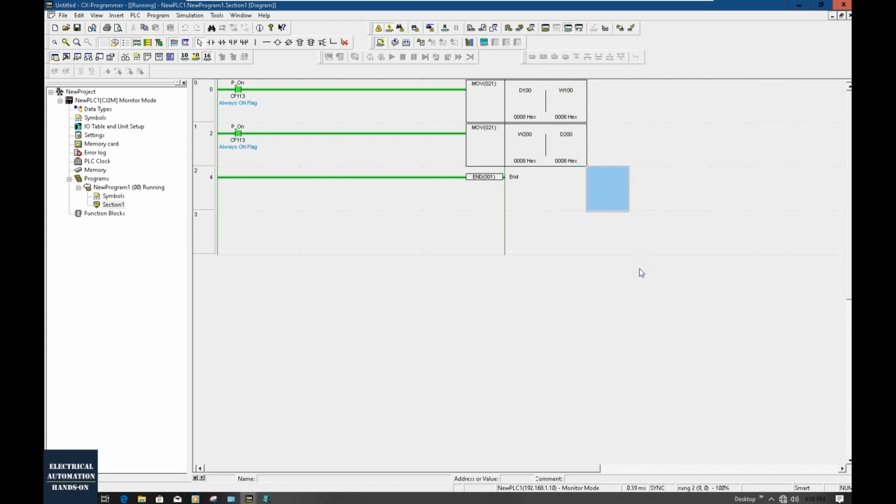And if our logic has some result and transfers the individual bit to the W address, using this move W200, we transfer this W200 to D200, and using Ethernet IP, transfer this D200 to that digital 8 output on the MURR device. So this is the typical Ethernet IP connection setup and logic processing.